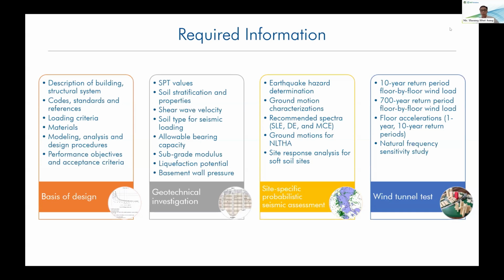That part is additional to the normal code-based design. We have to carry out the site-specific assessment for the seismic input. The consultant provides us different response spectra for different levels of earthquake. Normally, they provide service level earthquake, design earthquake, and maximum considered earthquake. For the maximum considered earthquake, they provide the ground motions to be used in the nonlinear time history analysis. If the building is located on soft soil, they also carry out the site response analysis to check the amplification of the ground motions due to soft soil.